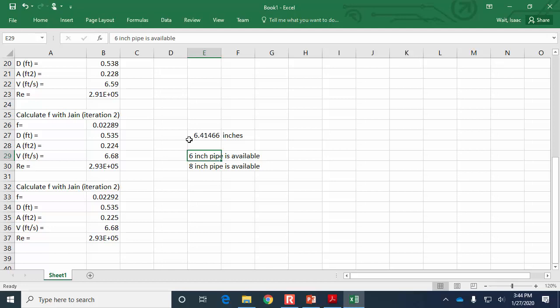How does having a smaller pipe affect the resistance? There's more resistance when you try to get the same flow rate through a smaller pipe. So the answer is, if you use this pipe, the Q will be less than the 1.5 CFS that is needed. You won't be able to achieve the flow rate that they need.